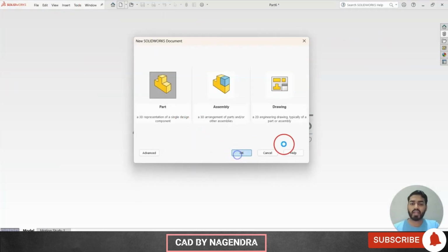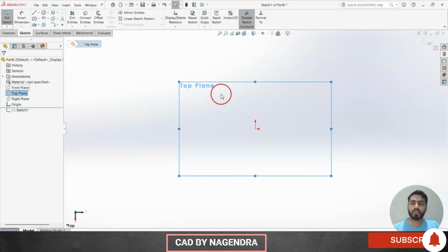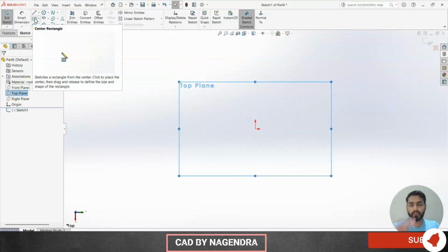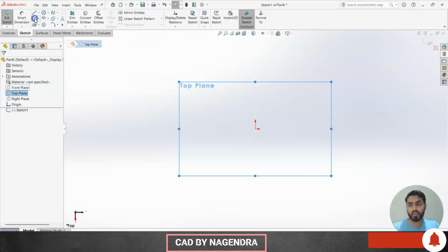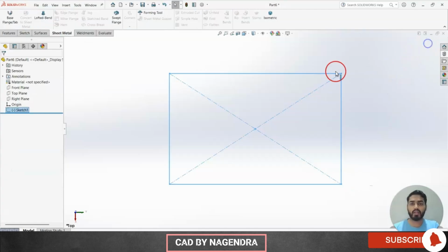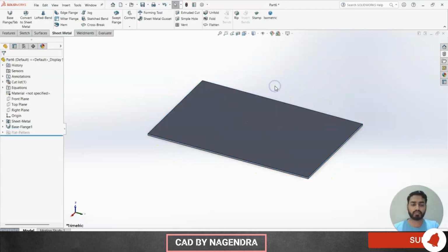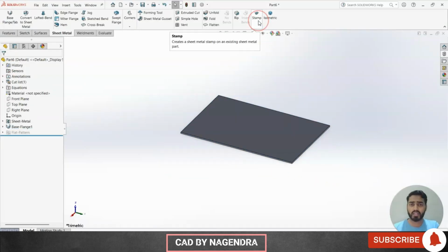If you want to create a stamping tool with our own shape, usually what we need to do is create whichever shape we want, again convert it into a forming tool, then only are you able to add it into the design library. Then we can drag and create the forming tool. But now by using this stamp tool we can create directly. So no need to go for part design, no need to create a tool, no need to convert to a forming tool. So directly stamp.